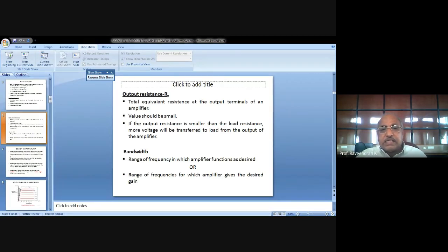VCC is equal to this particular current. V2 is equal to VCC into R2 divided by R1 plus R2, that we know. And V2 is again equal to VB plus IER, that we have seen. What is V2? V2 is the voltage across R2, isn't it? If V2 is the voltage across R2, that will be numerically equal to VB plus IER, isn't it? And IE is also numerically almost equal to IC because IB is very small, isn't it?